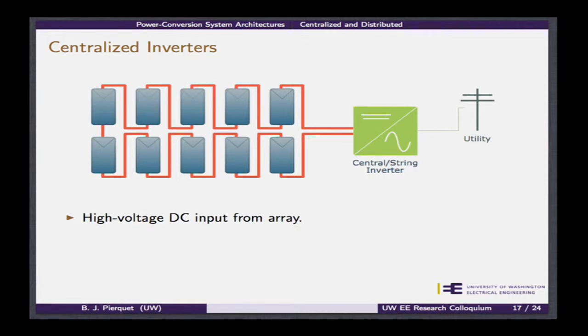But if you assume that it's 480, then it has to build a DC bus going into that inverter that has a value greater than the peak of the line that it sees. And so ultimately you're looking at voltages in the 300, 400, 500 volt range. So in order to get those, you have to have a large number in series. But we learned when you have a large number of these in series, you end up getting losses due to mismatch. And now that each one of these is geographically located across a larger area, the incidence of these essentially having mismatch are even higher.